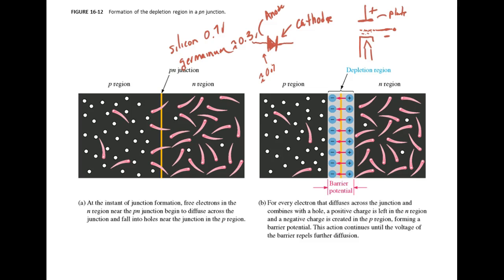And we forward bias these things, we set them up. We'll talk about bias in a second. But that's the symbol. This is supposed to be filled in for the symbol, by the way. But most people don't when they draw them because it just takes a little while. So this bar represents the what? Cathode, but it actually represents the N material. And then this side of the arrowhead represents the P material. And that's our symbol.